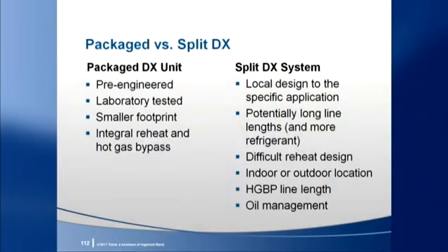The obvious advantage to a packaged product is that it's pre-engineered, whereas the split is typically a local design. A local design can be optimized for the specific application, but the package unit will be lab tested and its footprint is probably smaller if the split uses outdoor products. Refrigerant line length is always an issue for splits, and often needed requirements for both hot gas bypass and reheat make the number of lines, length, routing, and cleanliness important factors to the success of a split system.